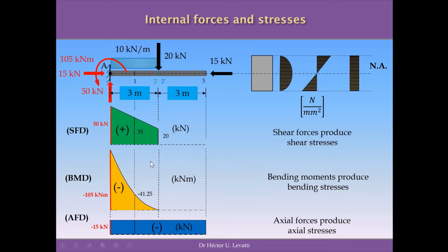So definitely for this case, and clearly studying the diagrams, the shear force diagram, the bending moment diagram, and the axial force diagram, this section is the section that is subjected to the maximum internal forces. So this is the cross section that we are going to study in more detail in terms of stresses in the first place.